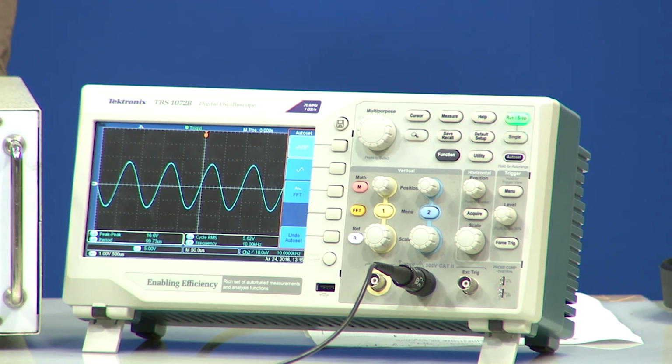So, 2.2 is the gain. Around 13 volt is a single side excursion, correct? 13 volt single side excursion means 26 volt peak to peak. So, 26 volt peak to peak divided by 2.2 will give you the input voltage at which saturation will start to occur, which is 26 by 2.2, less than 13 volt but more than 12.5 volt.